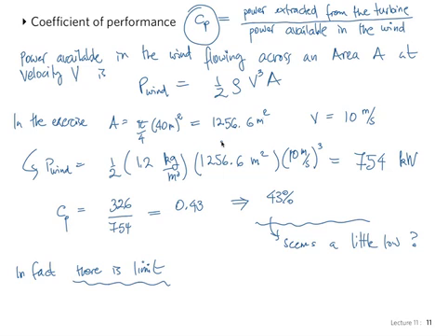If I just wave my hands at that problem, let me explain it this way. The wind, when it's going through the turbine, cannot really stop dead to zero, right? So for that reason, you intuitively understand that we can't take all of the energy from it, right? Does it make sense? So there is a limit. There's a physical limit to what even a perfect turbine could take. This turbine takes 43%, which doesn't seem like too much, but how does it compare to that limit is the question that we need to answer. So I'll show you how to calculate that limit in a moment. Yes?